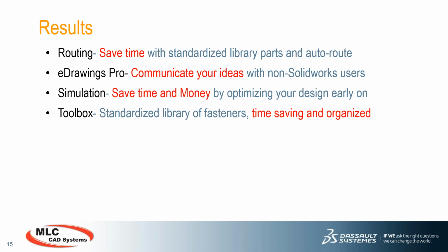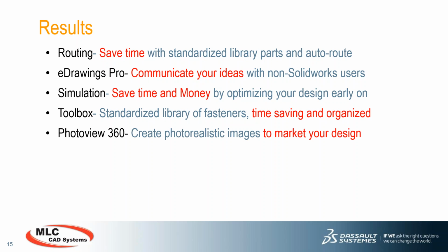Fourth, we use SOLIDWORKS Toolbox and its standardized library of fasteners. The Toolbox is time-saving and it's organized. Please do not spend time modeling fasteners in SOLIDWORKS. Use the Toolbox. It's easy to use, drag and drop, auto size, and it's far more organized than any of us could ever hope to be.